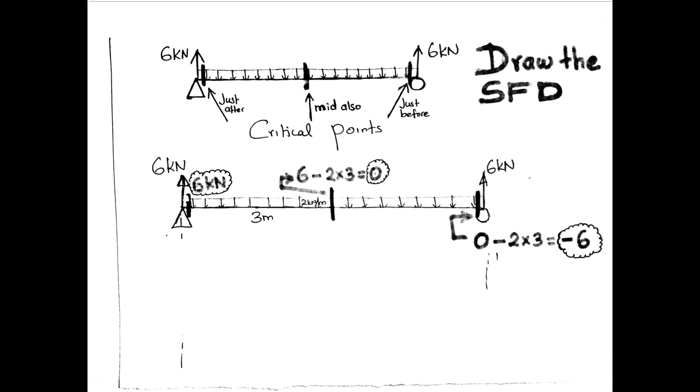Okay, consider left to right movement. Shear force shortcut techniques. Here this is 6 kilonewton upward, therefore plus 6. This distance is negligible just after the support, therefore there is no influence of UDL here. This is the UDL. Therefore 6 kilonewton upward, 6 kilonewton.